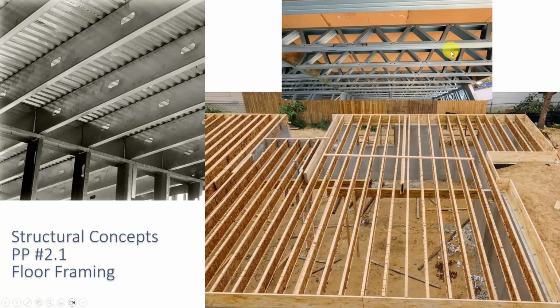And this is a picture of a house that was framed in. We talked about the footing and foundation plan. This is showing the rim board. It's showing the sill plate with the anchor bolts. These are wood I joists, or TJI joists. And you can see, since they're made in a factory, they can make them span much longer than you can get with a straight 2x10 or 2x12. This is an engineered lumber beam.